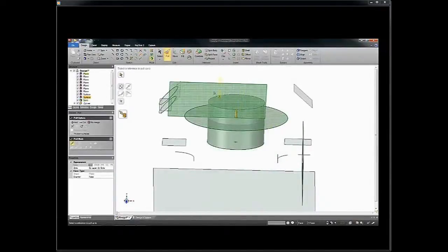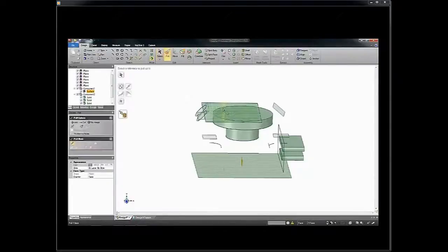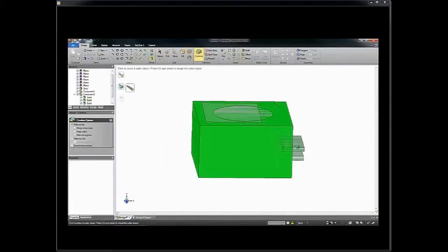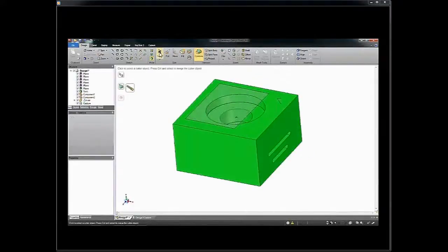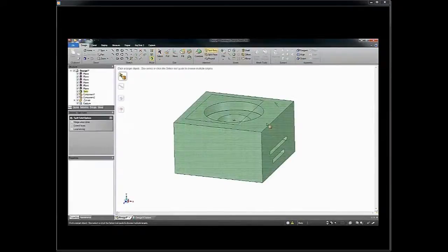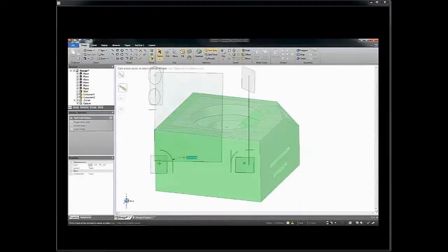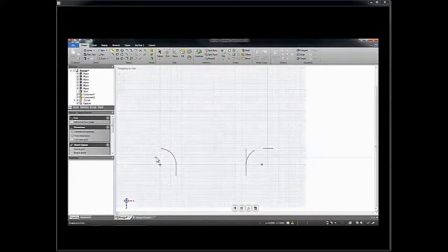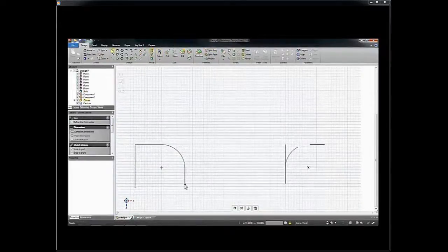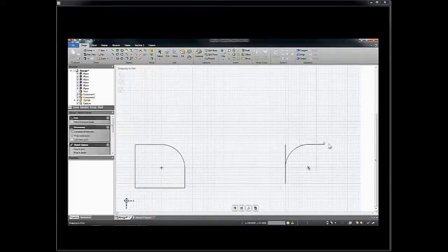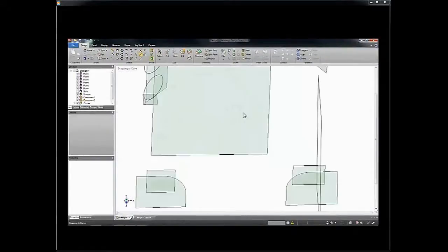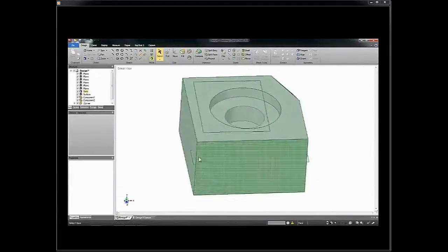So here's an example where the user created a simple sketch of a square, and then they're going to go in and start creating the solid geometry after he's put the arm down. At this point, he's collected all the information with the probe, and now it's just time to do what you saw me do before, which is simply convert those curves into solids or surfaces and start Booleaning, or combining, to subtract pieces or add pieces to it. So again, you take the sketch geometry, you can add a little more to it. You can use the intuitive snapping, cutting and sketching tools to repair and complete sketches if you didn't do the whole thing, because a lot of the sketching tools that are very nice, very intuitive in SpaceClaim are right there at your fingertips to use.